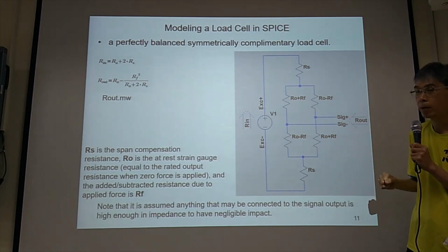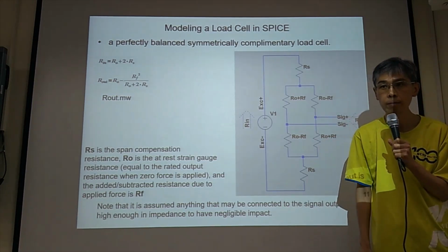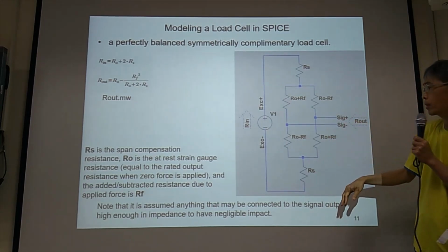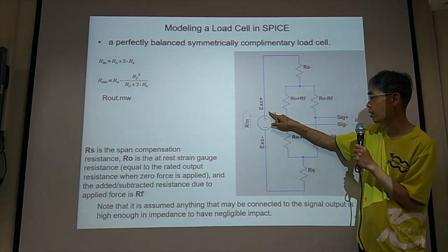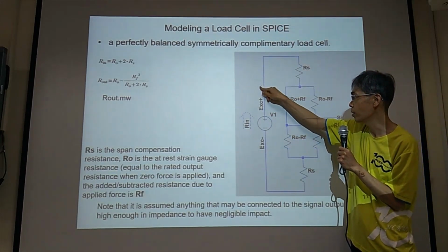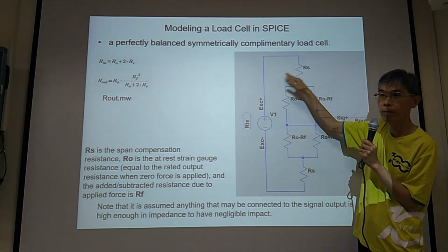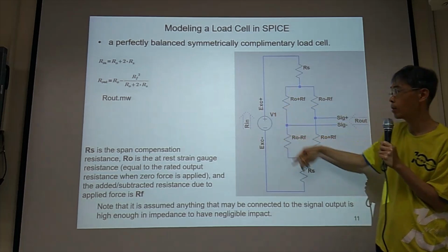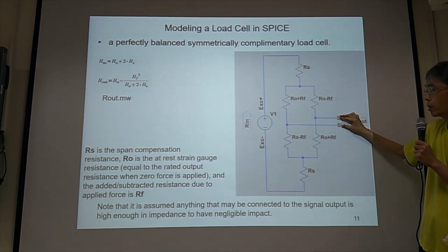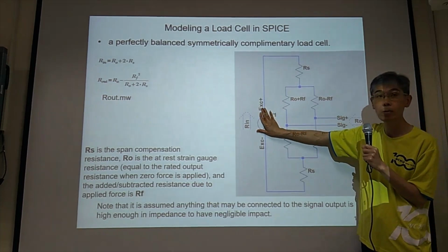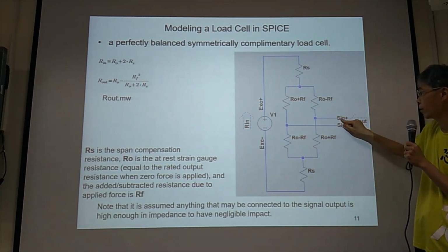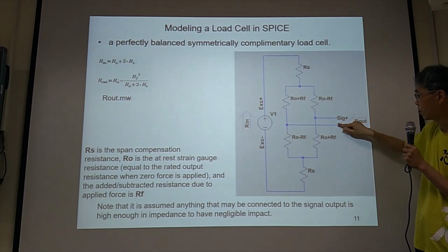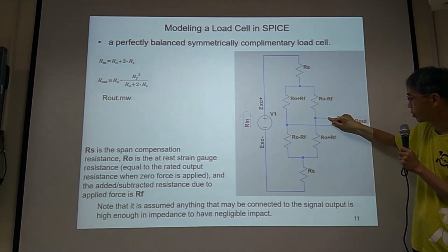Please calculate the input resistance and output resistance of this circuit. For input resistance, you can put V1 and I1 here, so you can do the math. V1 divided by I1 is the input resistance. For output resistance, you can remove this one, then apply Vout and there's a current Iout. So Vout here and Iout goes in.